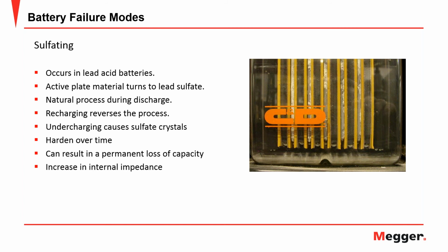Now, you may hear of times of doing what's called an equalization charge or a boost charge. These are where you raise up the voltage on the battery to a higher level. What that is intended to do is to break down sulfation crystals. That's what the intent of that is. And as they break down, you regain some capacity. However, the longer they remain sulfated, the harder it is to reverse them. If the plates remain sulfated or partially sulfated for a long enough period of time, equalization or the boost charge will not work. It's actually going to take a chemical process to do it.